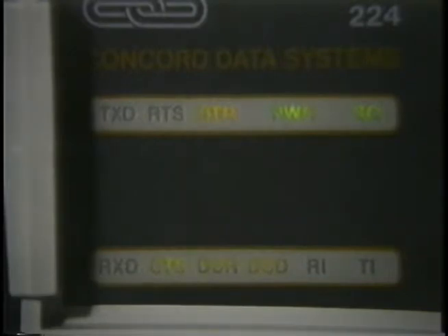Modems with signal quality retrain automatically and continually monitor the incoming signal level. When the signal level becomes too low or the noise level increases to too high a level, the modem will automatically attempt to retrain or retune itself to the incoming signal. Signal quality abort applies to some dial-up modems. These modems can be optioned so they disconnect a dial-up call if the signal is too poor for too long, perhaps 5 or more seconds during a call and 15 or 20 seconds during call answering.